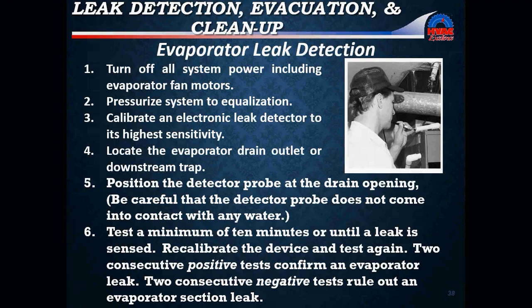Test a minimum of 10 minutes or until a leak is sensed. Recalibrate the device and test again. 2 consecutive positive tests confirms an evaporator leak. 2 consecutive negative tests rules out an evaporator leak.